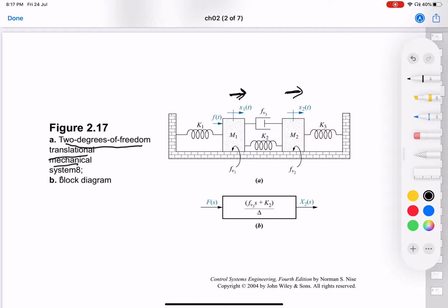In a similar way, if you fix the other displacement, in the sense that you don't allow m2 to move, you fix m2, then you have to ask yourself, if I make x2(t) equal to 0, can I move x1? Can I allow the displacement x1? And the answer is yes. You can still move this mass around. So this tells you how many degrees of freedom this mechanical system has, and when you know the number of degrees of freedom, you can write down the equations of motion.